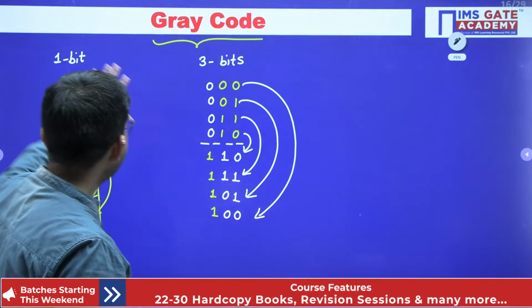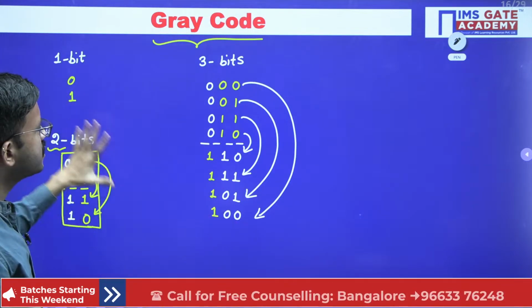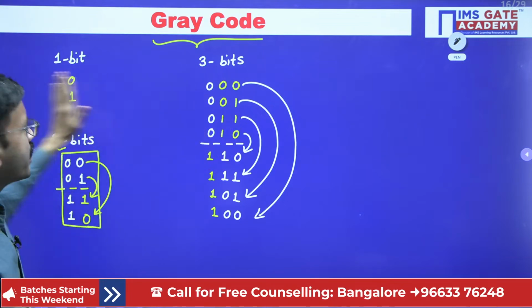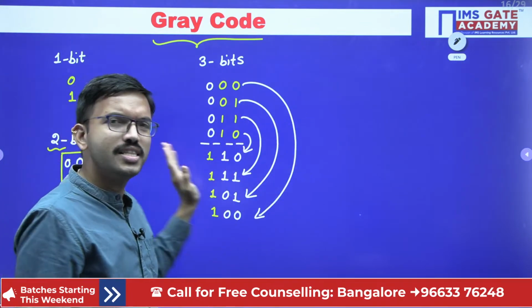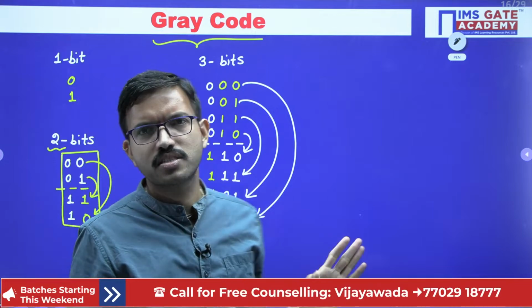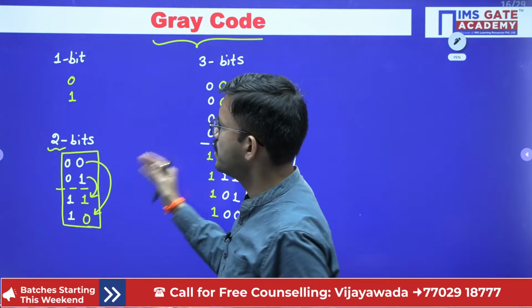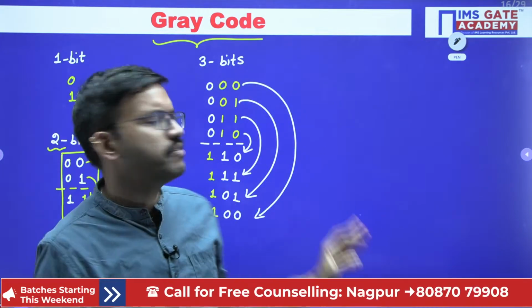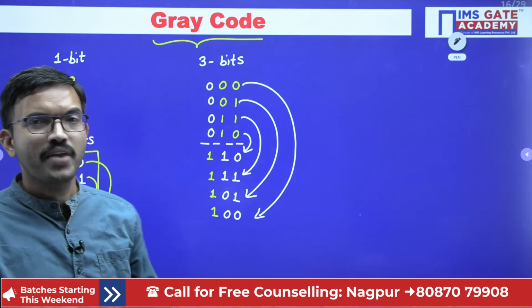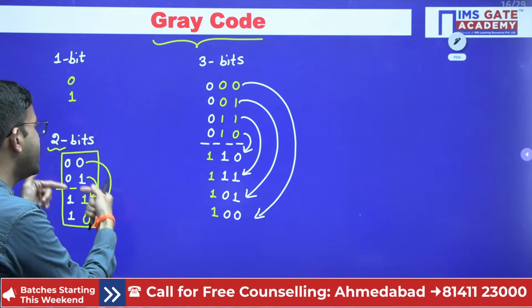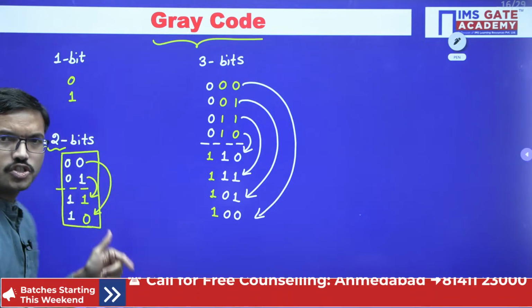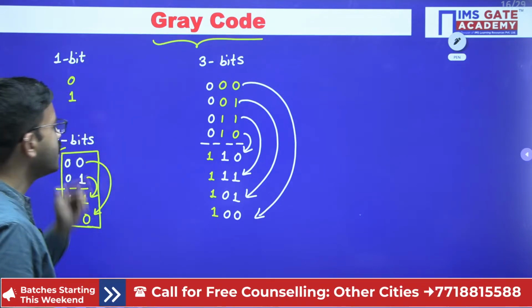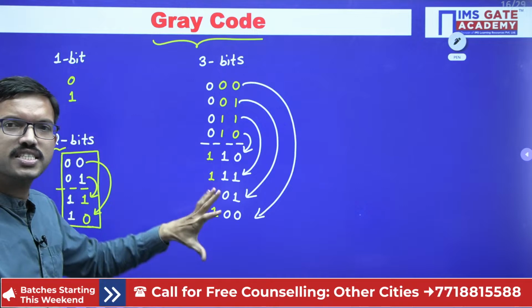Whatever code you arrange here, this code is nothing but gray code. You can formulate the gray code in this way for any number of bits. In this cyclic process, step by step, you can extend and formulate based on the requirement. And here, while creating the example for a unit distance code, one more property is inherently there, that is the cyclic code, right?